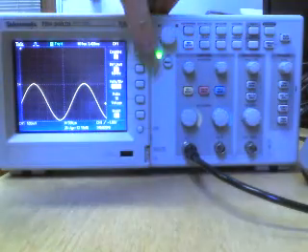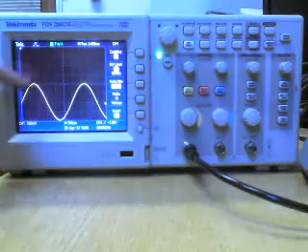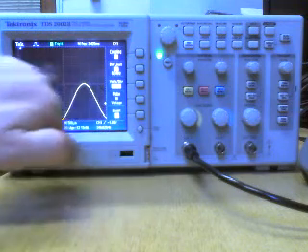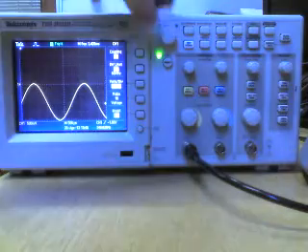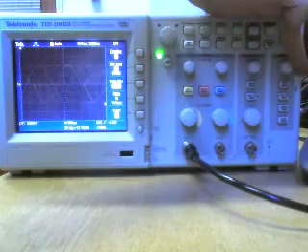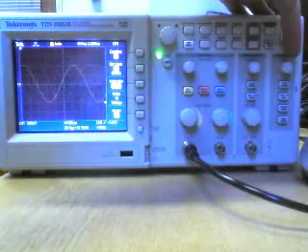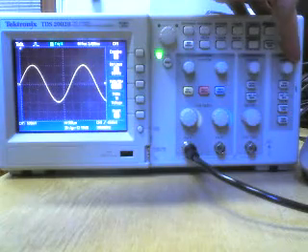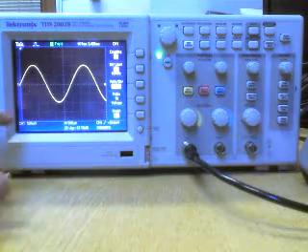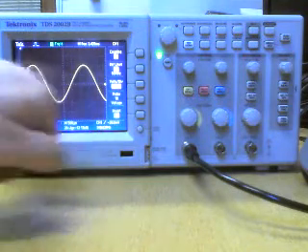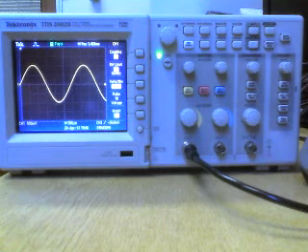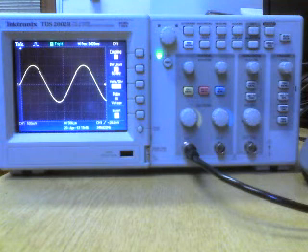Very simple. Just like before, you've got your DC coupling, it's showing you you've got a DC offset, it's below our 0 line, which is still up here. You can still see our arrow, channel 1, pointing to where 0 is, and it's shifting it down. And again, you can change coupling to AC coupled. In the case of the digital one, it doesn't shift the voltage trigger level with it. You have to just re-trigger. And there it is, AC waveform measured exactly the same way, voltage, time. It's got rid of the DC component, and all that you're displaying is the AC. Simple.